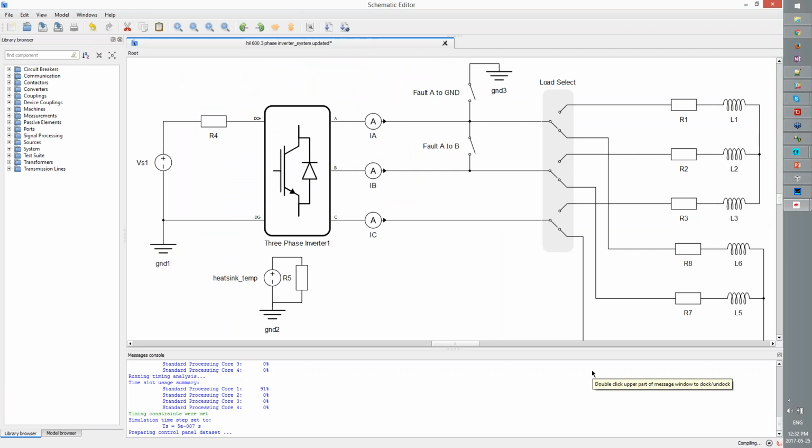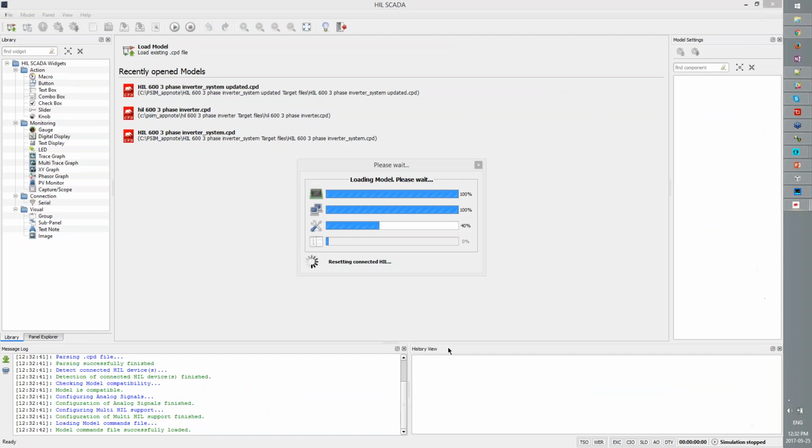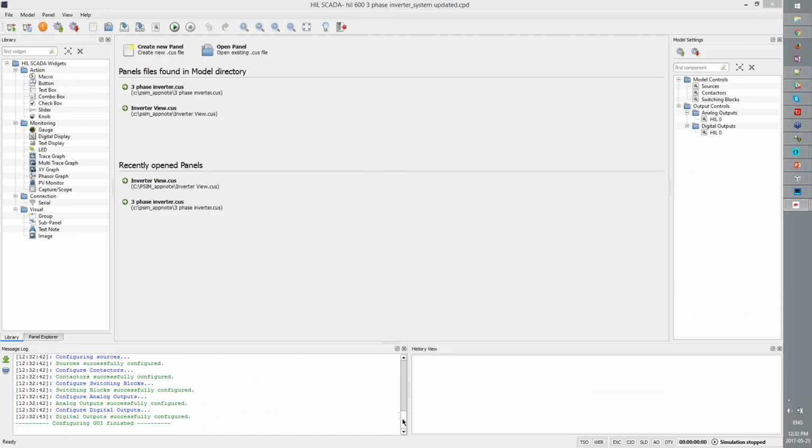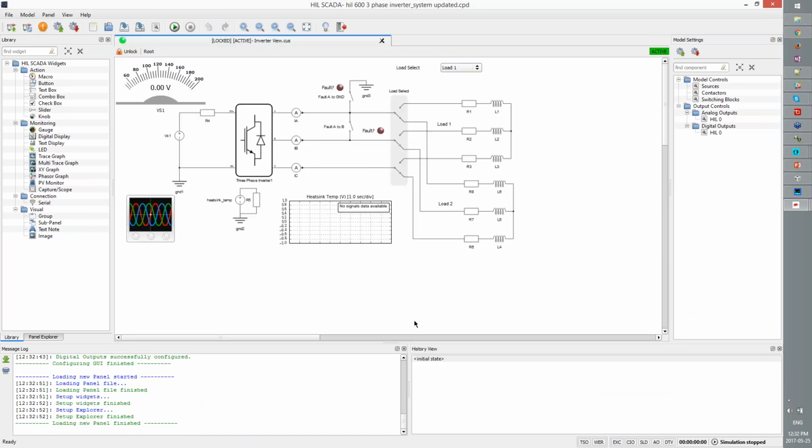So this model looks like it's compiled at 500 nanoseconds. So that'll be our fixed time step running on the FPGA. So this model will be running on the FPGA at 500 nanoseconds. And the digital inputs, this is pretty important, are actually sampled at 20 nanoseconds. So this basically provides us enough Nyquist, so there's enough resolution to get about 10 bits resolution there.